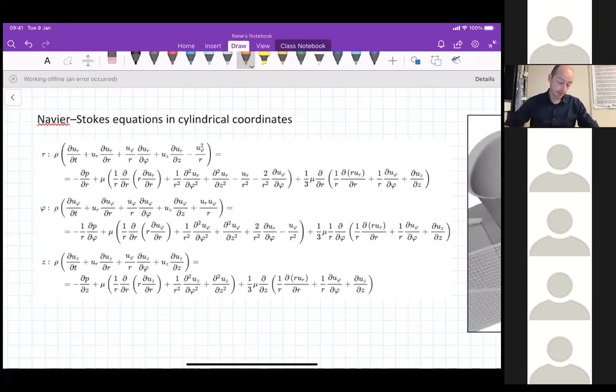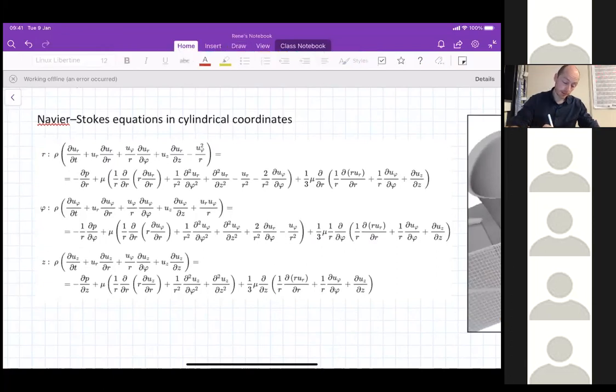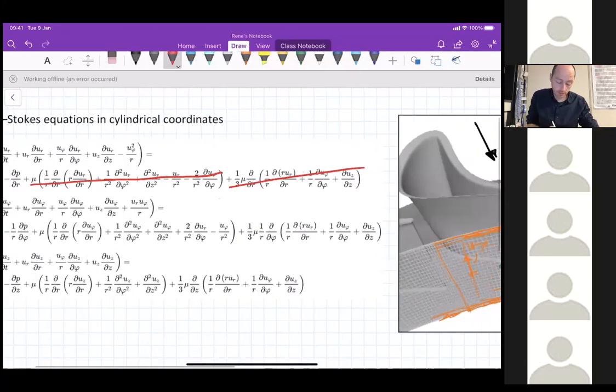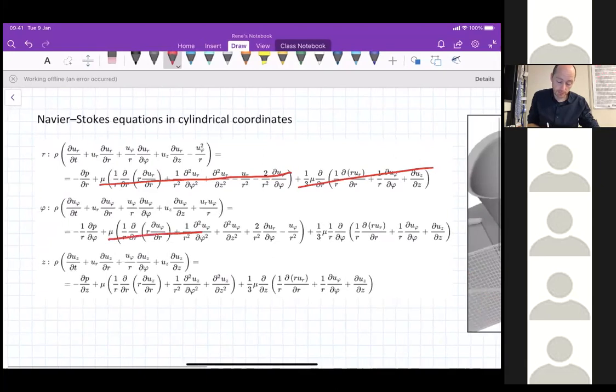Or you can derive them in Cartesian coordinates, you can derive them in cylindrical coordinates, or in spherical coordinates even, or any coordinates if you want to make it more complicated. But we said now that we can neglect the effects of viscosity because we are staying away from boundary layers, and we say the velocity has no gradient, then the shear is zero. So viscosity is not really playing a role. You can cross out these terms and things become already much easier.